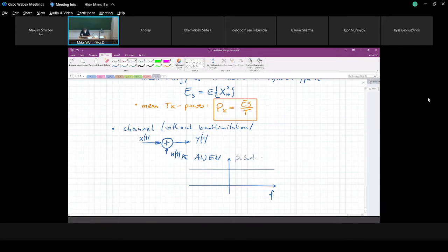And we usually use this symbol here. We do this tomorrow in communications engineering. Fourier transform of the autocorrelation function. We use this capital Phi. And then here I use this capital N to say it's a process, but I'm talking about the power spectral density of the noise. And this depends on the frequency f. Okay, and now this may look a little bit strange, what I wrote here. There is a parameter which describes the noise, and this is N naught by 2.